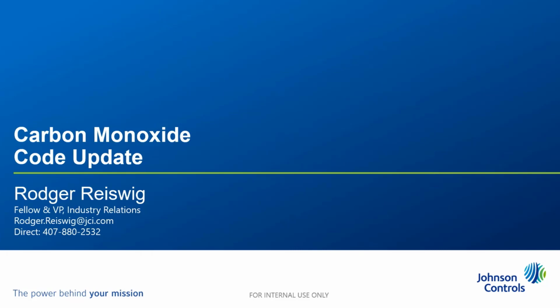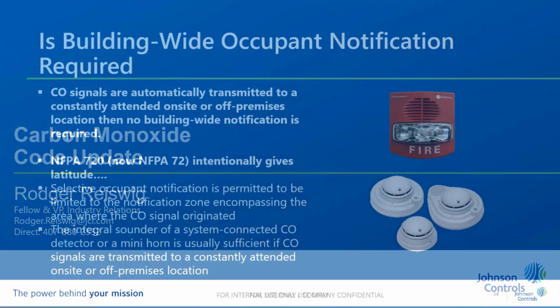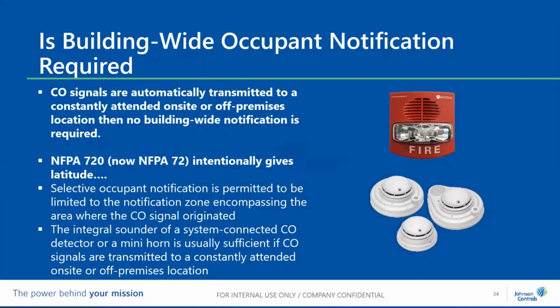Question. Roger, this is Dave Henry. I got a quick question. You show the smoke heat CO sounder all as one unit, but from what you're telling me, you can also get by with the upper left unit that's a smoke heat CO and have all your sound come through the addressable notification device as individual appliance controls in place of that, correct?